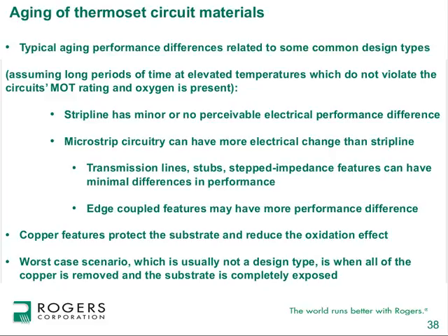Most of the microstrip circuitry that really doesn't change much with long-term aging is like transmission lines, stubs used for impedance tuning, stepped impedance type of features, things like that. But the features that are more susceptible would be edge-coupled, kind of like the slides I showed a little bit ago with edge-coupled bandpass filters.